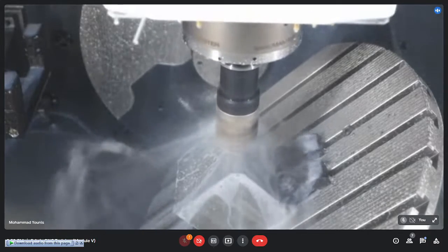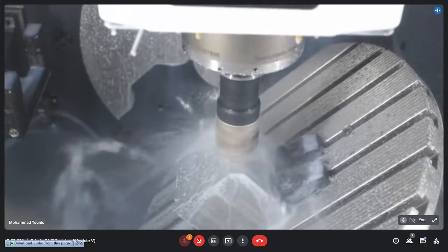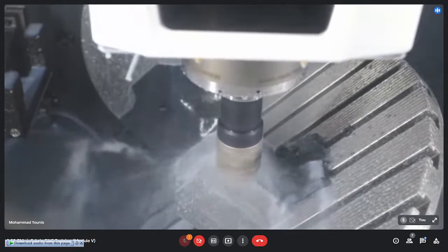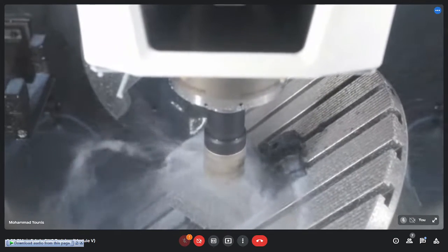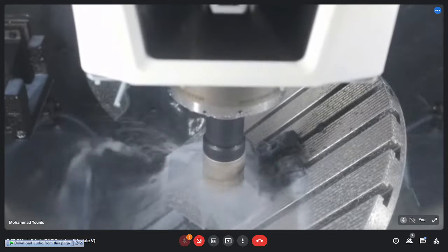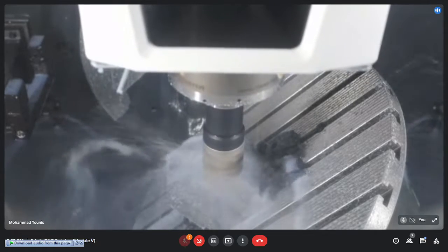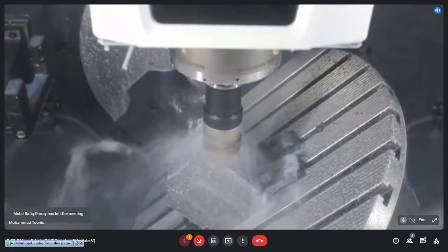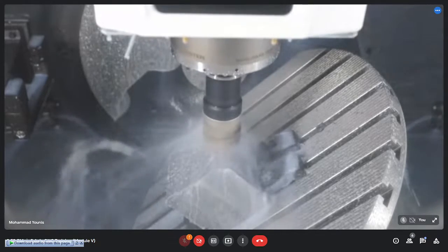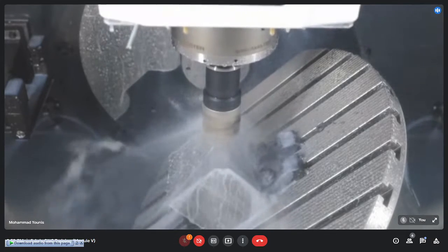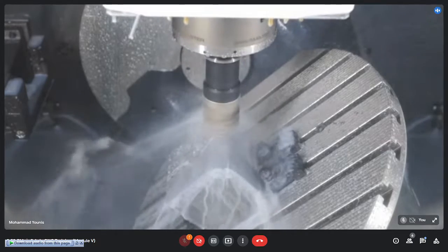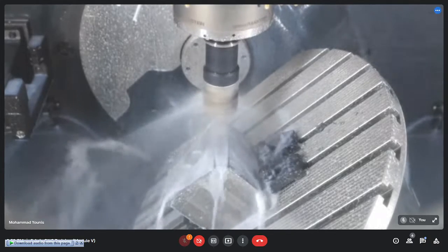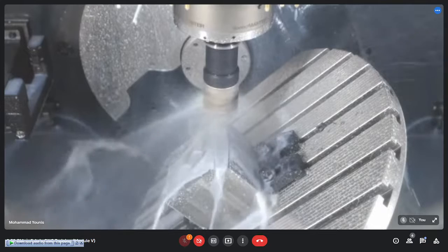So if we talk about a 3 axis machine, there you don't find this possibility. You don't machine there at some angle. So this is only possible here on this 5 axis, because this chamfer milling or the machining at some angle can be only done by these two additional axes, B and C axes.